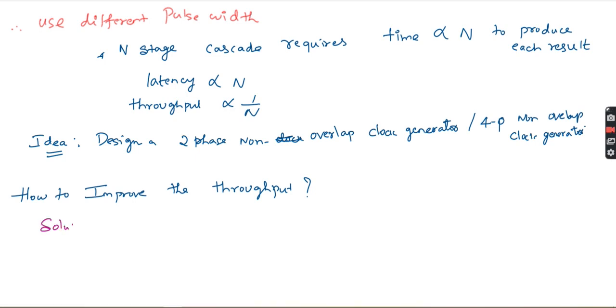The only solution is to use a pipeline technique. Use a pipelining system or pipeline logic. What is meant by the pipeline technique? We have to use a latch to hold the input of the respective stage. So we can say we use conventional latches.